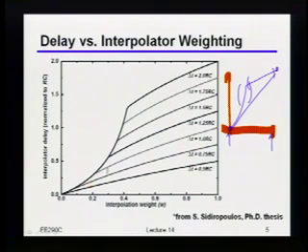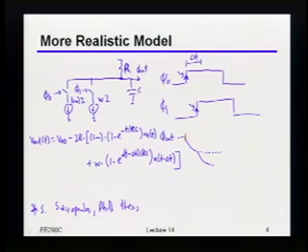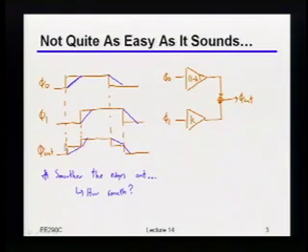Because as I start moving up, as I start increasing that delta t relative to the RC, what's happening is I'm getting more and more of this curvature over here, right? Now, by the way, as hopefully should be clear, this curvature here is just associated with the fact that we have that first exponential, right? So basically, the more we're letting that first exponential settle out, the more we're getting this kind of weird nonlinearity in the delay, right? Which is, again, very much associated with this picture that we drew over here, okay?